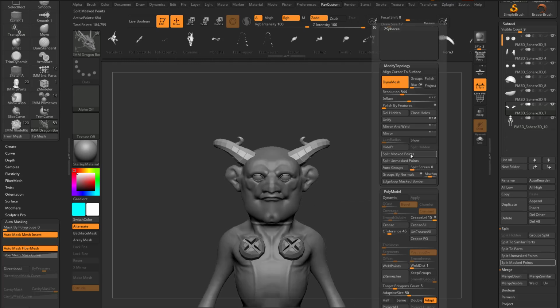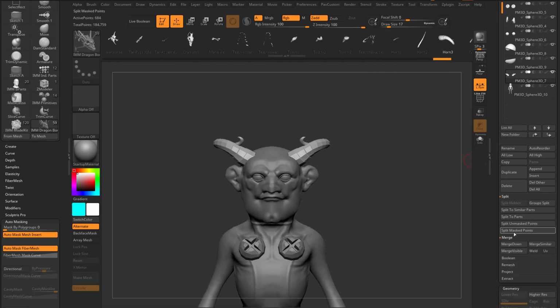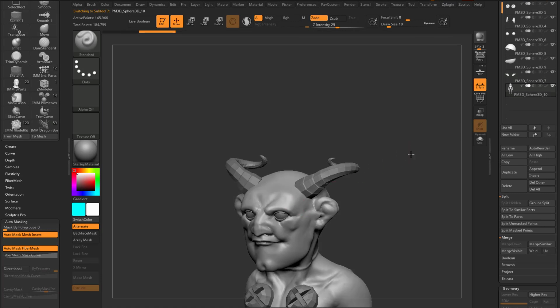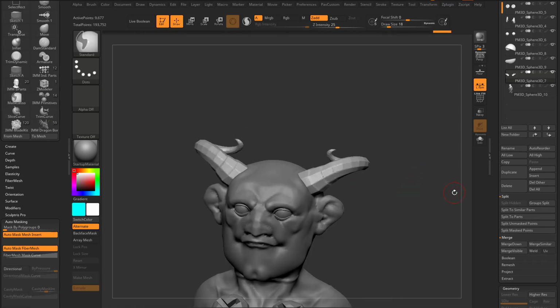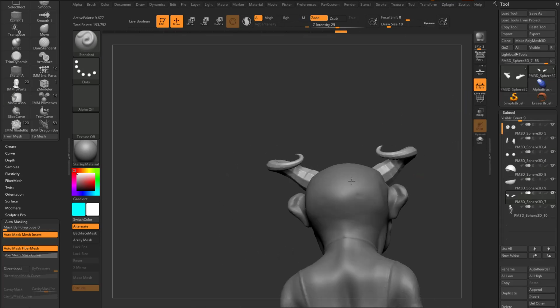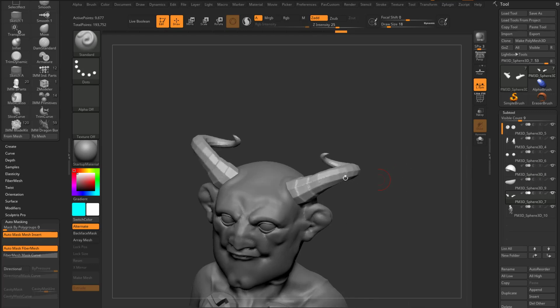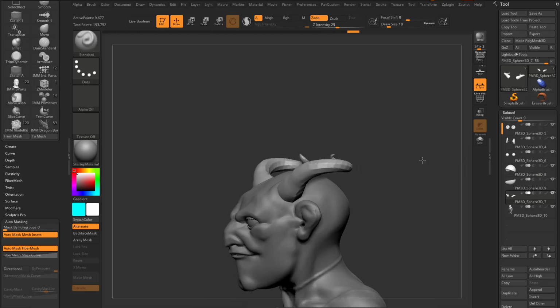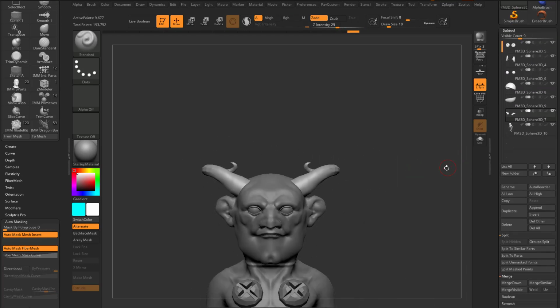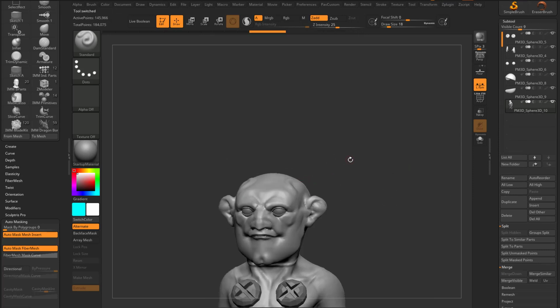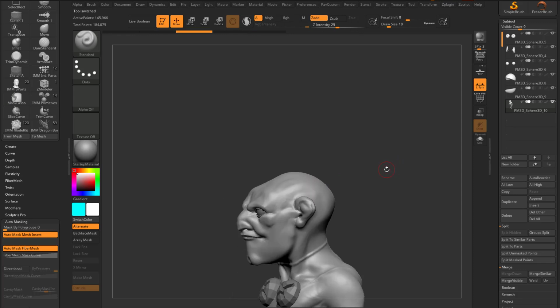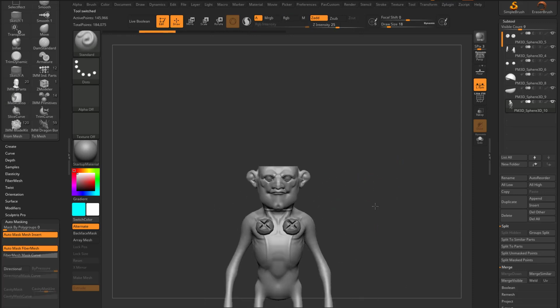I'm going to do a quick split mask points down here, and you can alt tap on this head, go through here and sculpt, you can alt tap on the horn, you can control drag because Dynamesh settings will already be set because you dragged it on something that already had Dynamesh properties, and you can sculpt this separately as well. If you don't want to use these, of course you can delete that subtool here, and on this subtool we can just Control Z to undo those changes.